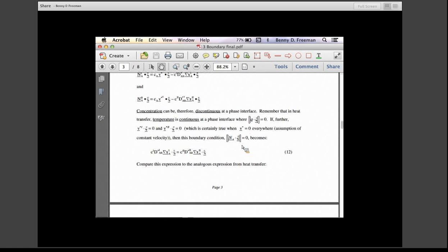One would be, we looked at this problem of liquid flowing down a wall and calculating basically the rate of absorption of a gas into the liquid as it flowed down the wall. It's a falling film absorber, essentially. And we said at the liquid wall interface that there was no flux of the components of interest into the wall of that device. Well, that's a case where the velocity in both the solid, that wall, and in the liquid right by it, the velocities there are zero, right?